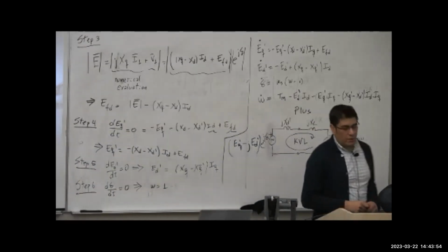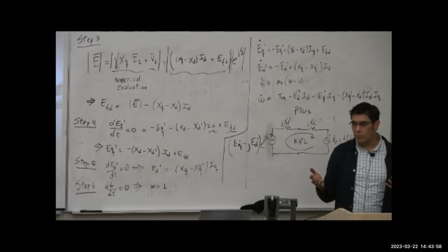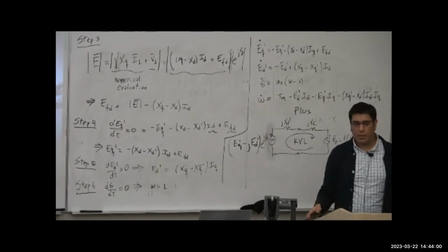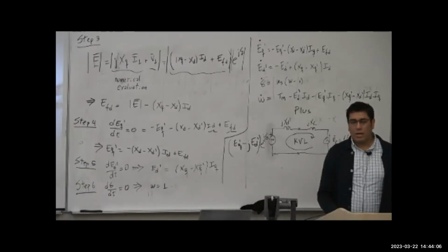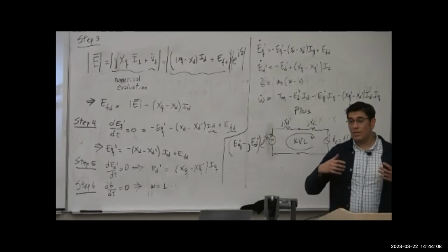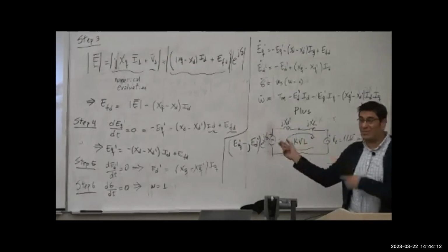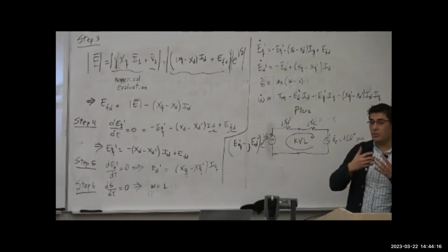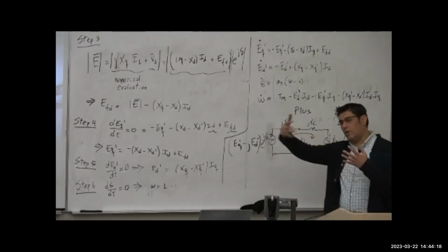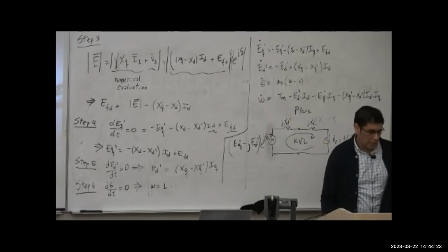All these steps, you can find this step also when you run dynamic simulation in commercial software. Have you played with PSSE? Some of you. When you do that, you need to do that initialization. What the software is doing is all these steps that we're talking about. And then when you do the initialization, you apply the disturbance and see how the system will move in time. The state variables will change in time.